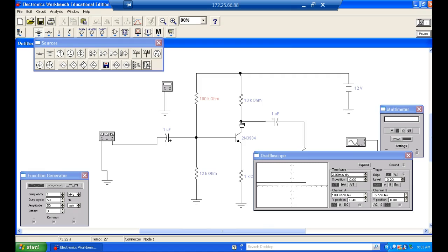That's exactly right, because there's no current flow. If there's no current flow, this guy right here is dropping how much volts? Dropping no volts. So I come over here and look at this guy right here and see it's sitting at 12 volts. Down here on my emitter resistor, it's going to be sitting at 0. If I come over and measure 12 volts right there, guys, I know the transistor's cut off. Right? Everybody okay? Makes sense.